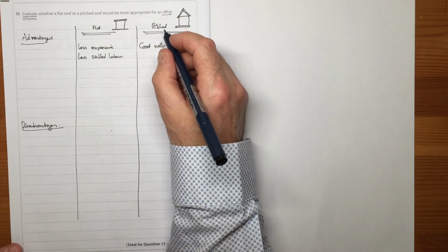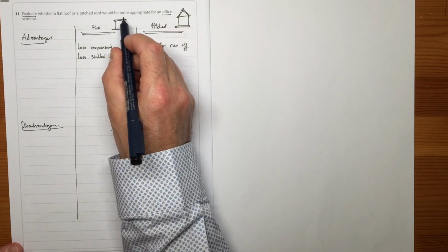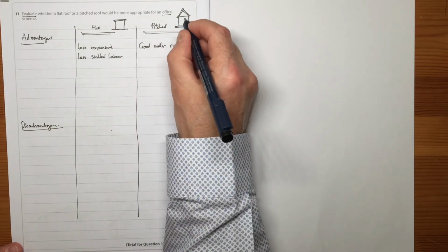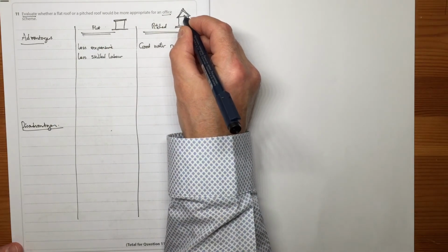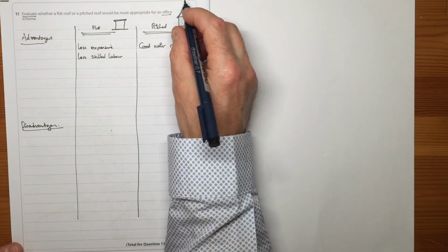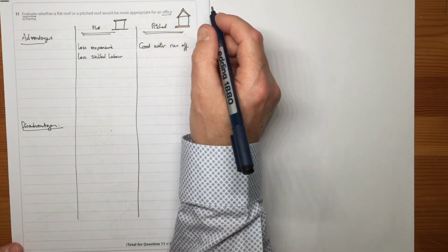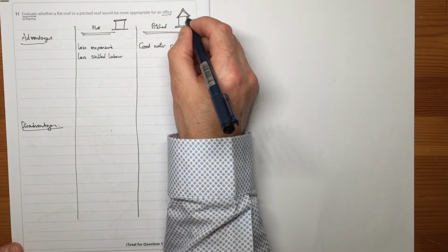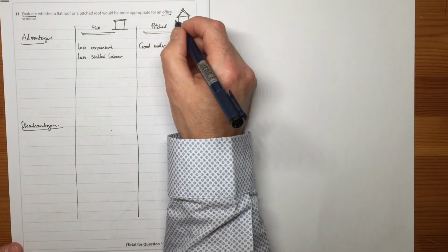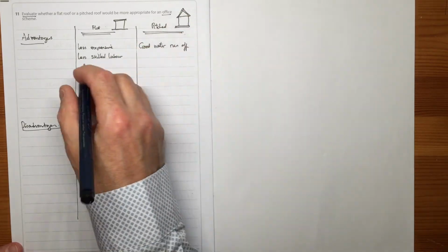And you could argue that a lot of the work on a flat roof can be done by one person or a team of people with similar skills, but not a pitched roof, because you've got to put the structural timbers up and form the actual shape, and then of course you've got to clad it externally with the tiles and the felt, and then lead flash it. So even for an office building, even if it's metal decking they may use, sheet metal work, it's still a more specialist, more expensive fabrication method.